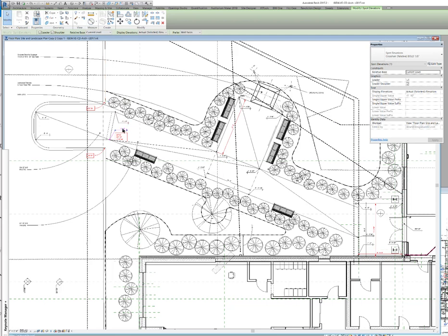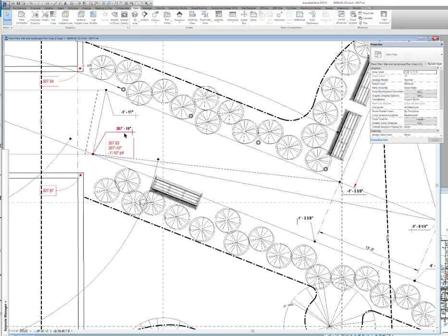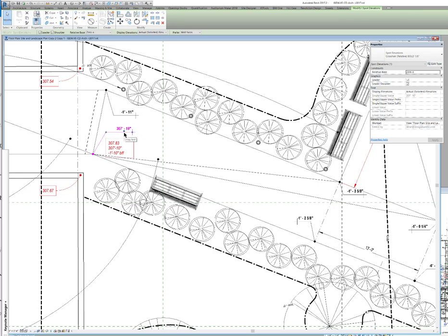What is the elevation set relative to? I have it set based on the current level, which is first floor. So I'm at negative 1 foot 10 from the first floor. But I could set it relative to 0, and that would give me the helpful elevation that the layout folks need. I have it in feet and inches because it's simpler to work on this way, but you could create another one that's fractional feet and inches, which I've actually already done in my tag types.